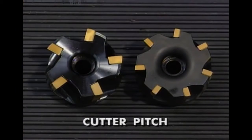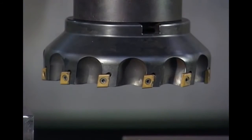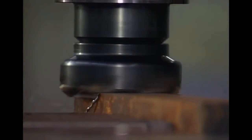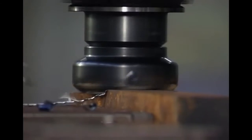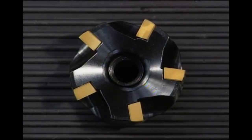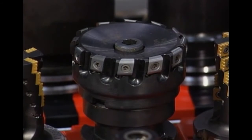The pitch of a milling cutter is determined by the number of inserts in relation to the cutter diameter and can be defined as the distance from a point on one edge to the same point on the next edge. The coarser the pitch, the larger the chip gullet. Gullet size is important in face milling, since the chips are generally confined to the gullet until the insert exits the cut. Cutters may be coarse pitch, fine pitch, or extra fine pitch.